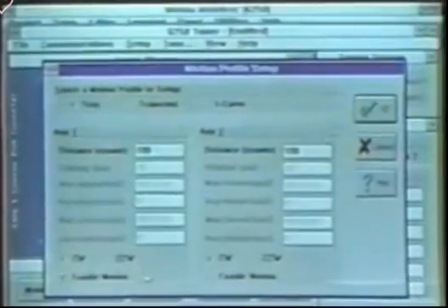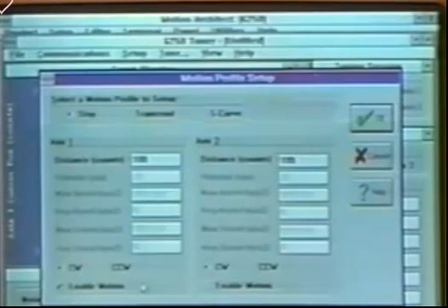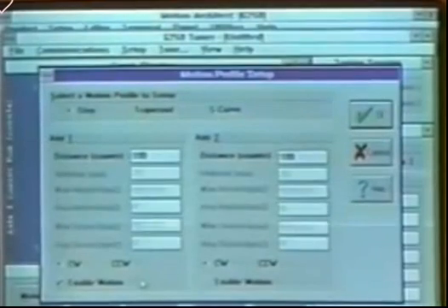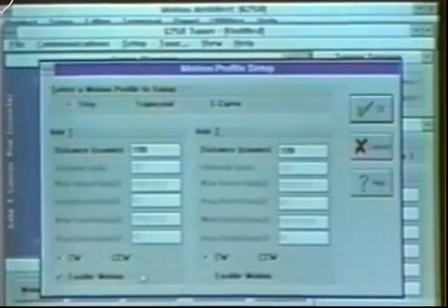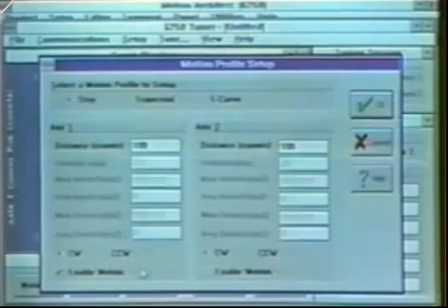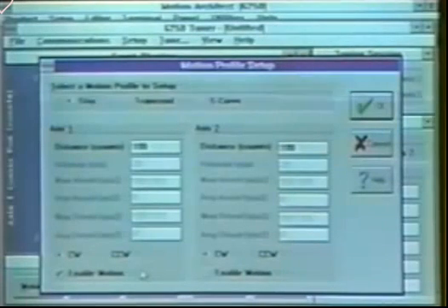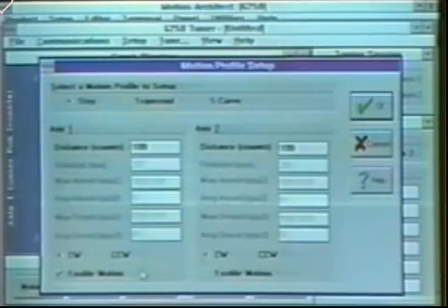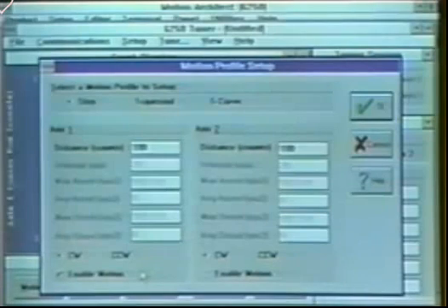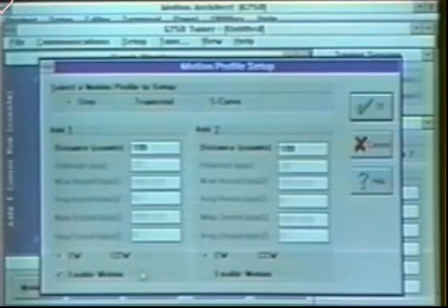We will go with the Step Profile. This move type typically gives the best representation of the system's overall characteristics. A step move commands a set distance with an infinite acceleration. This type of move will usually excite all of the system's characteristics so we can see its overall responsiveness. This can usually be used for the majority of the system's tuning. Small step distances are recommended to avoid saturating the analog output, which could disguise the actual system's response.